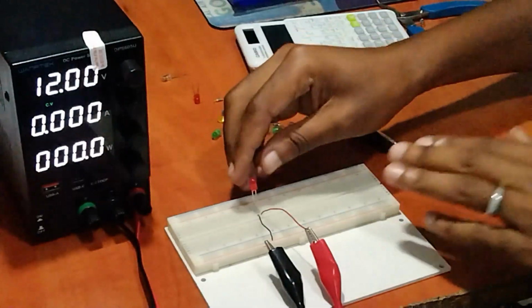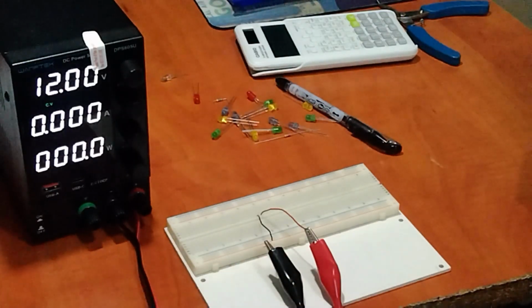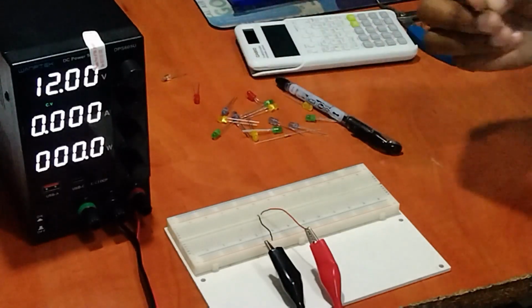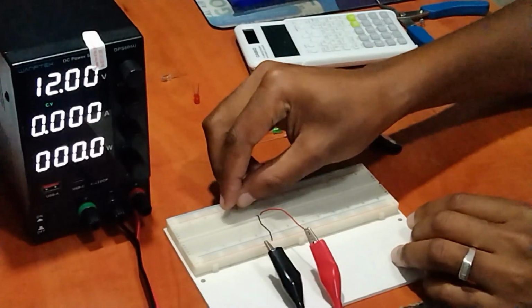And we need to power another one. If I put in another one here, even that one is going to burn, ne? Yes, sir. Because it only operates at 2.2 volt, ne? Yes, sir. So now I'll need to put a resistor. I already calculated prior to this, ne? Yes, sir. 560 will work fine, ne?